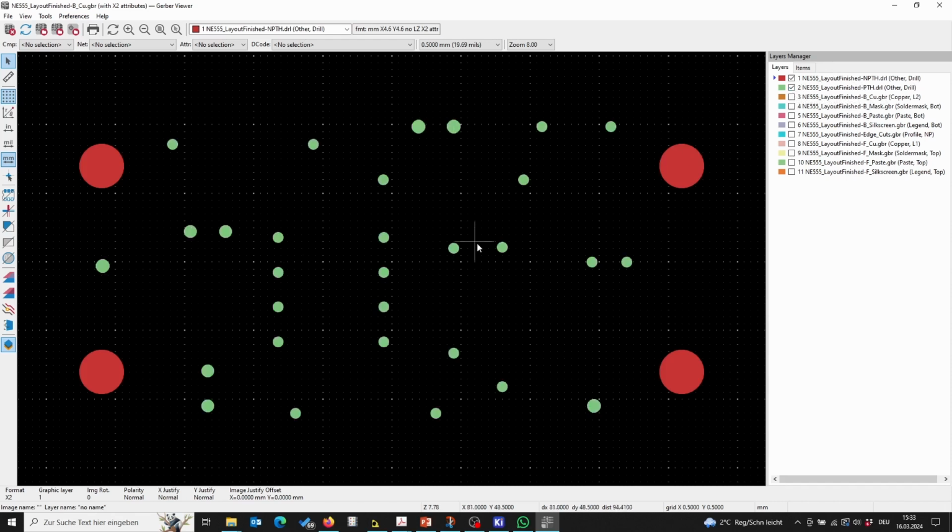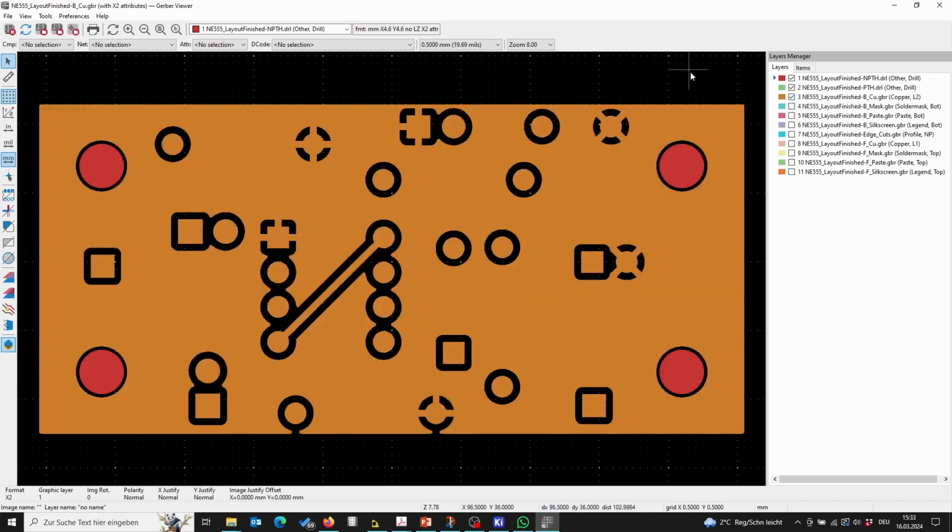And here you see our components values, the drill files. Then the bottom cover. Like if you use the blue arrow, you can set it on the drill files, and then you have the background, our copper, and then you see where are the drill holes, and you can see if at the package of your IC, all 8 drill holes are in the center of the copper, and so on. Okay, silk screen for the bottom is not so interesting.